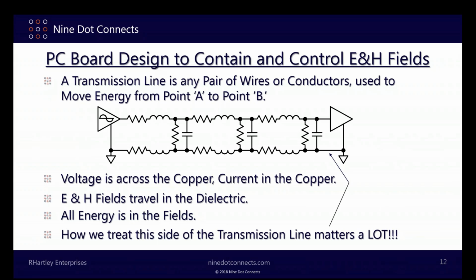What you do with the return side of this line, does it matter? Can it be a power plane? Well, yeah, it can be if you set it up right. Meaning what? Meaning if it's a 3.3 volt signal, it better reference a 3.3 volt plane.